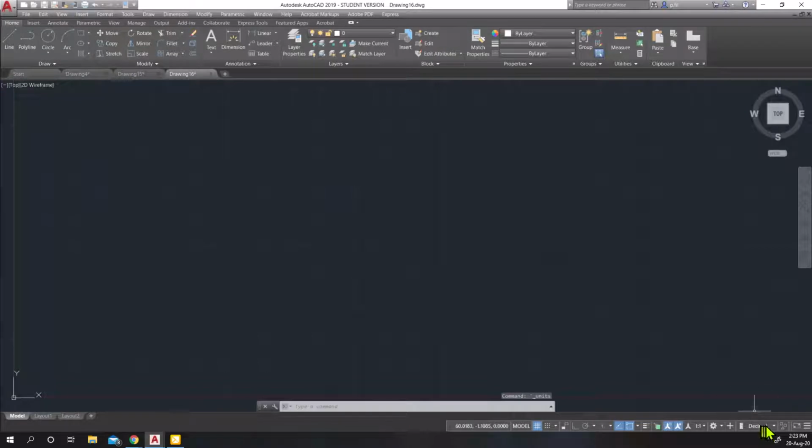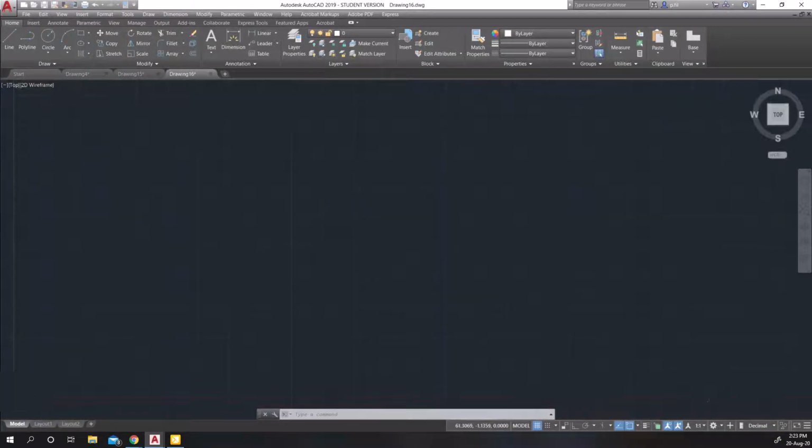Changing it down in the very bottom, you can do a quick version of that. The pop-up won't come up, but I can quickly change to architectural and quickly change to decimal or to any other unit, but I don't have control over the precision and accuracy components of those elements.